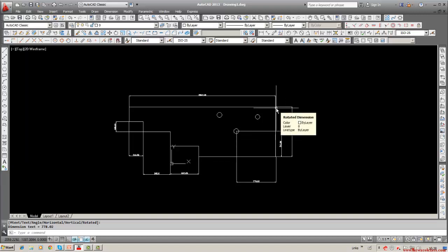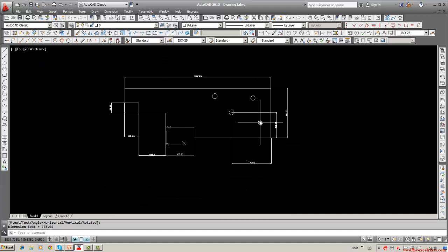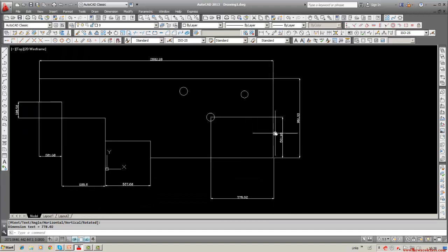If you are doing it in CNC, suppose you take this corner as a datum, then you need to know the dimensions of the holes and the edges, all from this point. If the component is dimensioned like this, then you have to calculate the distance from this edge to this center, vertical and horizontal, similarly from here to here, vertical and horizontal, and so on.